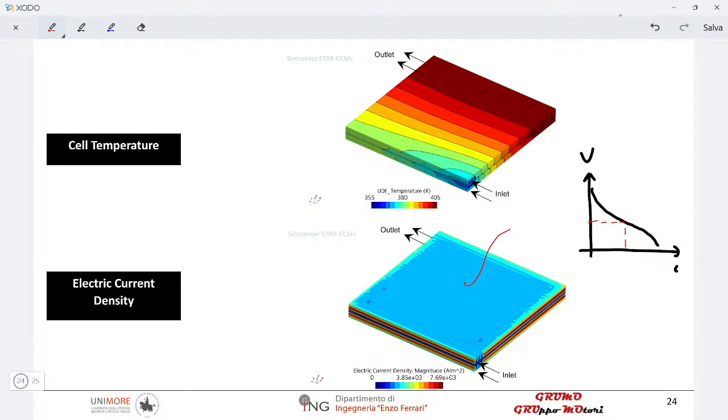You might identify, like in this operation here, local areas of overheating that lead to dehydration, that lead to poor ionic conductivity, so poor electrical generation. So all of these kind of considerations are really the battleground for CFD, and this is, I think this is the ultimate goal for the developing and knowing of these kind of models, okay?